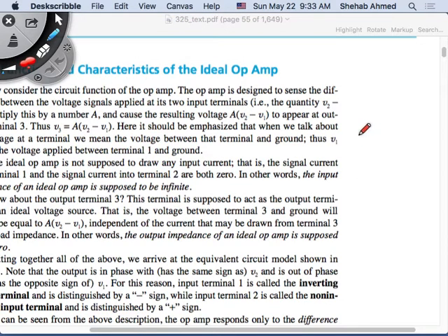Why 14? The op-amp will have minimum 3 terminals and then 2 power supplies. So the chip will have 4 op-amps, with a minimum of 3 per op-amp, so 3 times 4 is 12. And then there's a power supply rail that's common to the whole substrate. So they were talking about how many legs the chip will have, minimum.